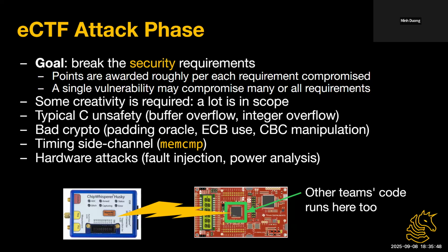And then hardware attacks. This is what's kind of hard, and we're the only other team besides CMU who I believe have executed this in the competition successfully. In particular, fault injection is what we're talking about. You can skip an instruction, or do something other than what was originally intended. So maybe corrupt some memory value. And another idea that I don't think anyone has done in the competition is power analysis.